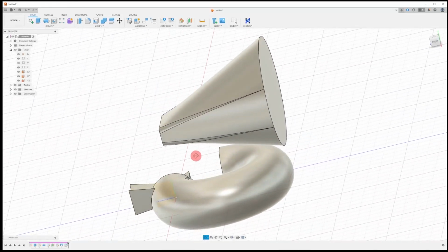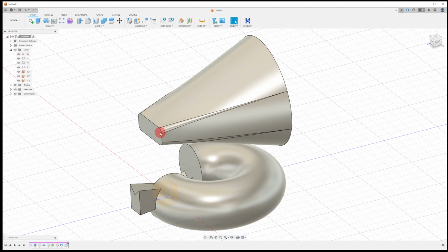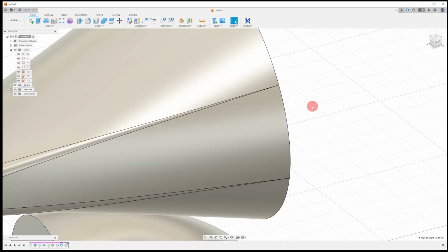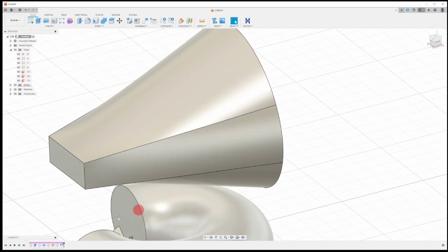Now, this is one way to tackle the problem. You can see that filleting has made this fillet larger, and then all the way at the end, the fillet disappears over the length. So I'm going to right-click and delete that fillet. And instead, I'm going to right-click on Sketch 3, the sketch of this shape.